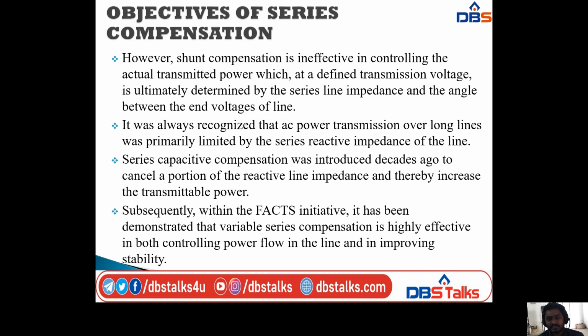Series capacitive compensation was introduced decades ago. This concept already existed decades ago. Why do we use series capacitive compensation? To cancel a portion of the reactive line impedance and thereby increase the transmittable power.